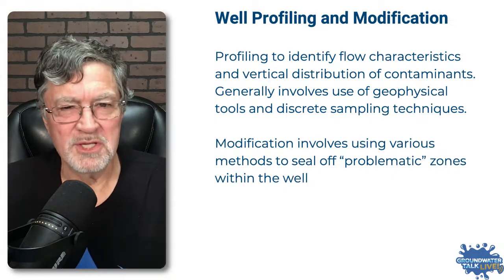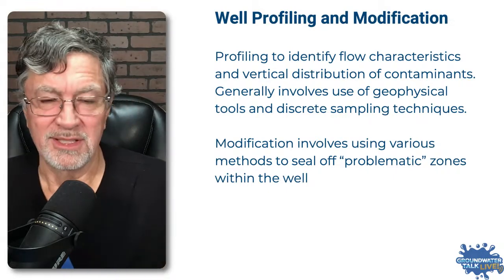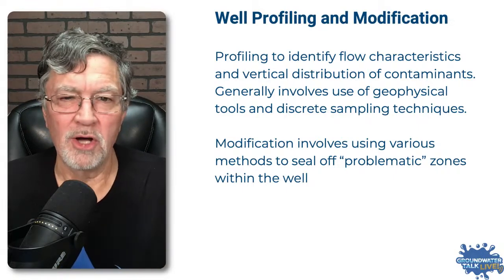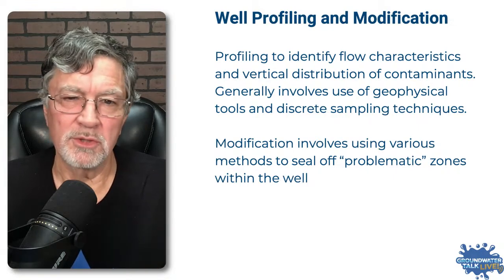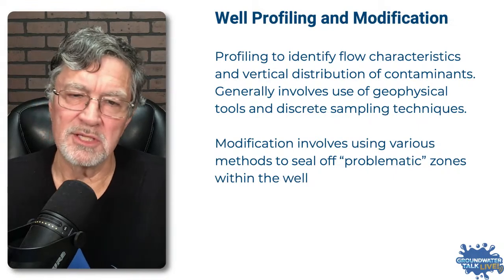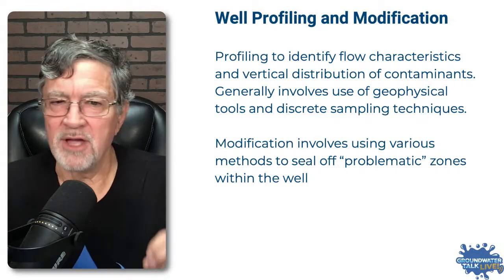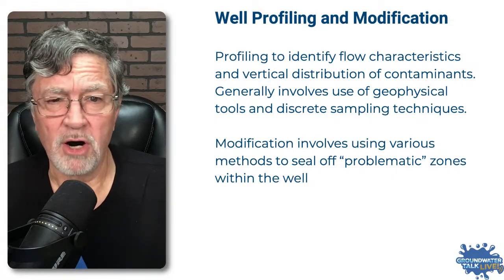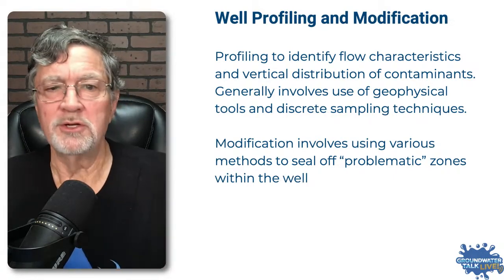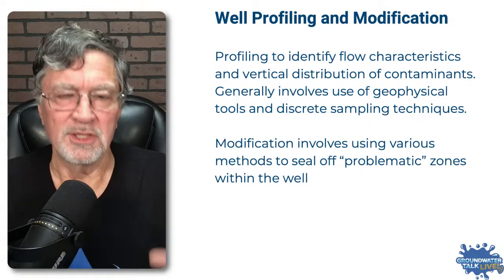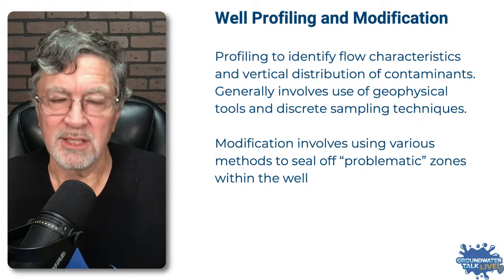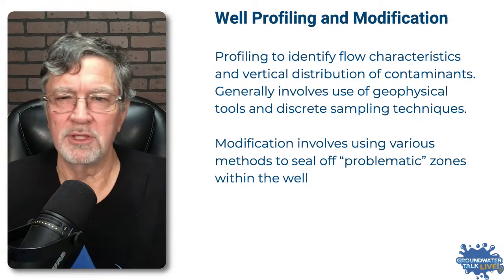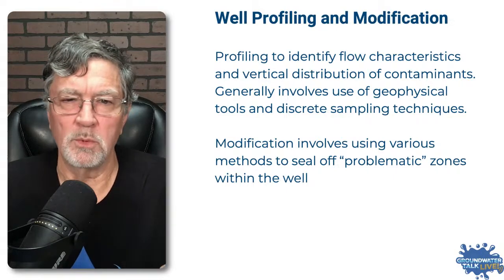We don't always have adequate well logs, and well log quality can vary all over the place. I like to look at the well logs and match things up so we know what the well construction is and what the geology is. But sometimes you need to go back. If you have an e-log, that can be very helpful. Sometimes part of the profiling can involve doing some geophysical tools so we understand what's going on behind the casing in the screen, so that we can get a good assessment and only seal off what we need to seal off to effectively reduce the contaminants coming into the well.